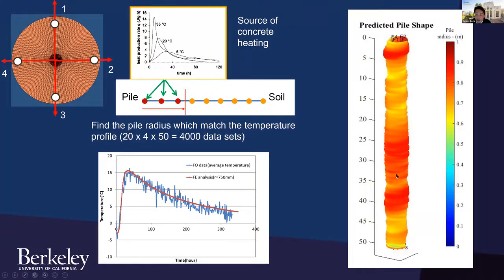And indeed, you see a better grip, or better shaft development, along here, which is in the sandy formation. But in here, you can see a little bit of necking. This is where we saw it, in the clay silty formation. But then here, it initially slips, and then it starts to engage some shaft friction.